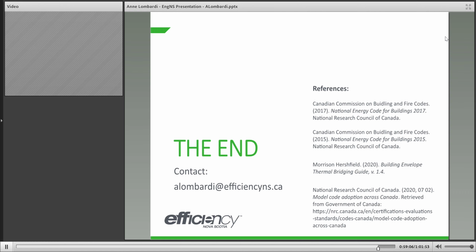Can you combine prescriptive and performance compliance pathways, and have you noticed recurring non-compliance issues? I can't really speak to the non-compliance issues, because I don't work for the permit office. But to the first part of the question, can you combine the pathways? As soon as you start down the performance path, you're committed to the performance path. You would use the prescriptive path if you can. If you're able to meet all those requirements, then you use that path. When you have any system that requires you to go down the performance path, you have to do that for the whole building, because it's whole building compliance.